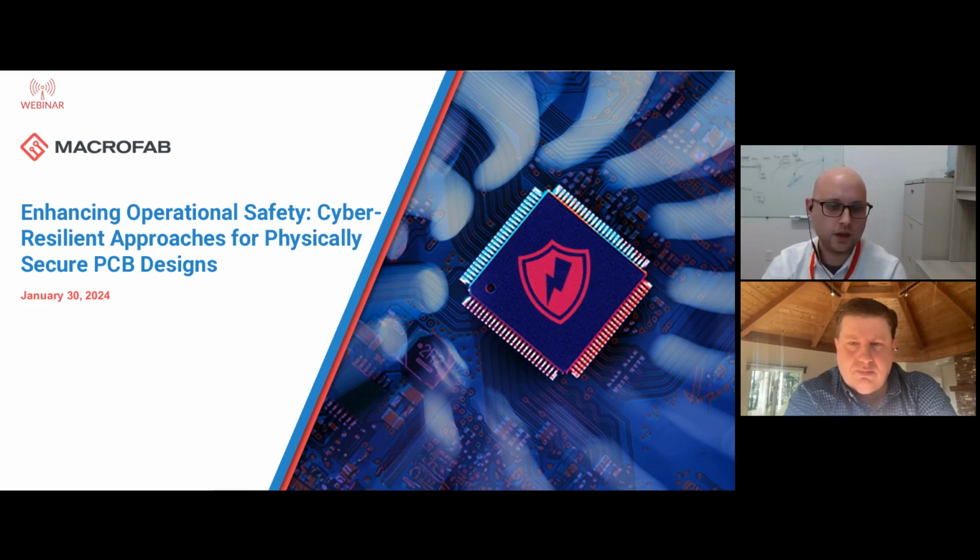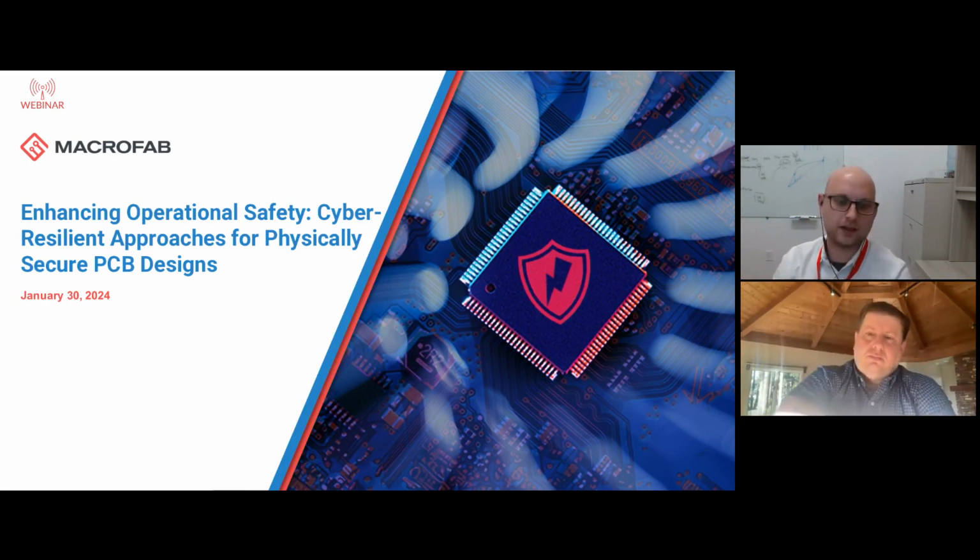When we talk about this, especially at the design stage, when we're talking about PCBs, the first step you should take is not just at the component selection and sourcing, it's really at your architecture phase, right? When we're talking about especially combo products with firmware and hardware, what kind of data are you going to be storing? Where are you going to store it? How are you going to update it? That initial phase of the architecture of your product is critical to determining everything that comes after that, right? If you're going to store some data off board in something else, maybe that's fine if it's not critical data. If you need to store critical data, it needs to be on the microcontroller, potentially in a secure module, things like that. So I would definitely start at the architecture phase.